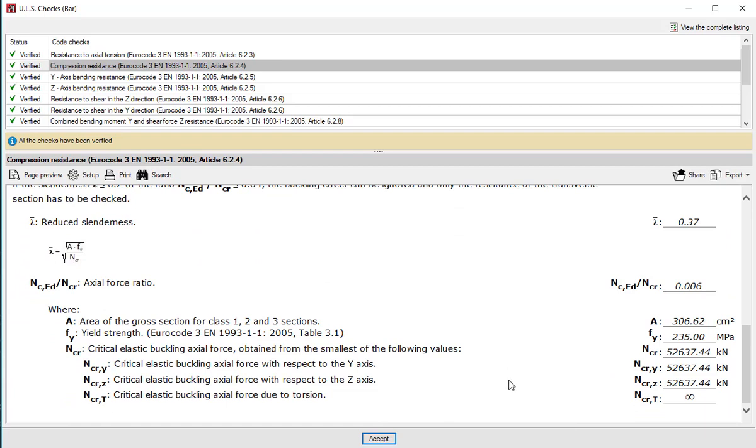If the section meets the building code standard, then a green check mark will appear next to the code. If it fails, then the program will show which variables do not meet the requirements. This feature is a powerful tool offered by CYPE 3D because it allows users to have a clear mathematical understanding of the calculations behind the project.